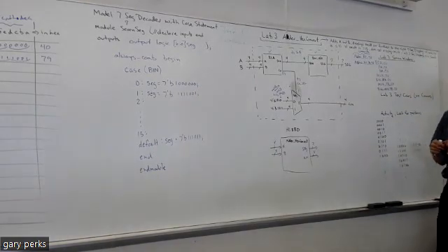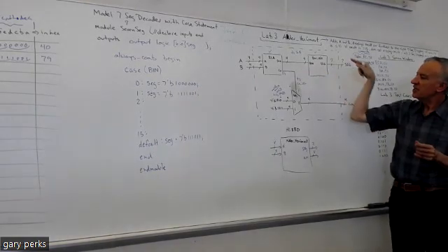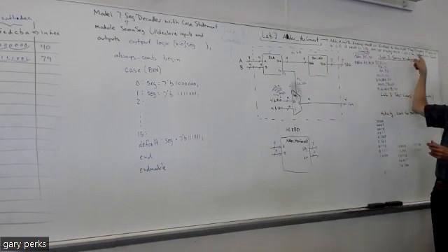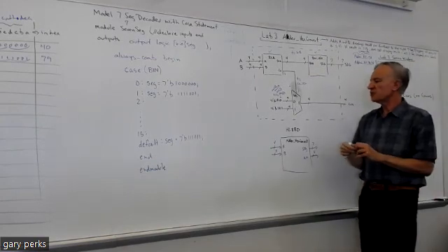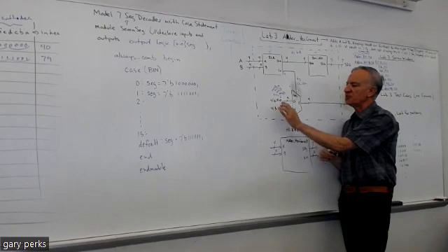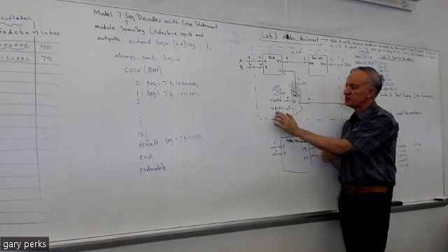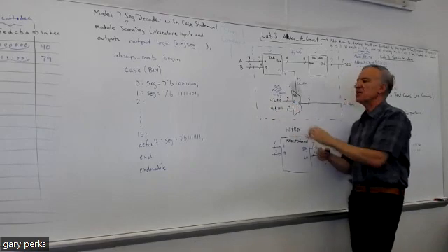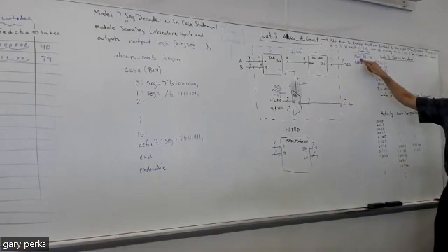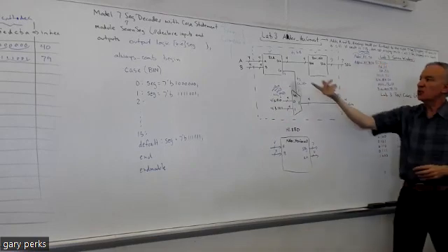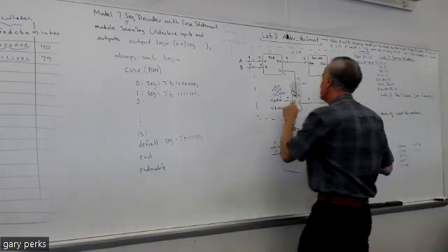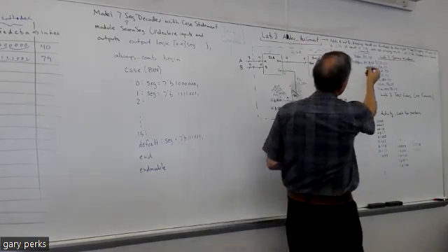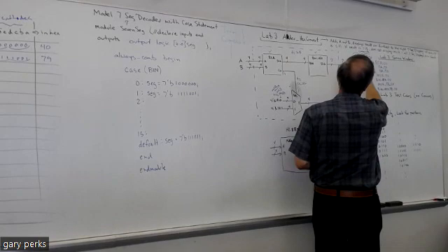Okay, so do you see how this diagram's connected gives us what we're looking for here? Now, the question that was asked a little while ago about how would you actually code this? How would you code having this data, this 1, 1, 1, 0 at this input, and all 1s at this input? Well, you do that in your top module, your structural model. When you're making all the connections between the modules, to make this connection, this would be in this design source right here, your structural model.